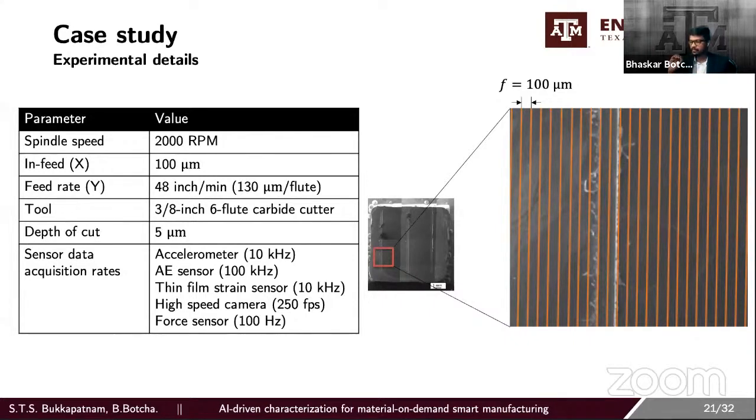I use a very minor 5 micrometer depth and just finish the sample using the milling cutter itself. All these lines refer to the feed of the macro milling cuts, so we are not referring to the micro mills yet. Did I answer your question?